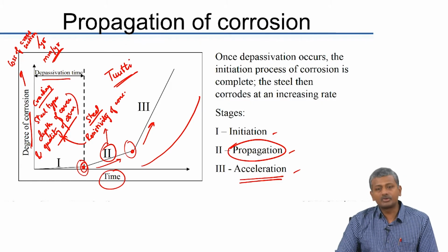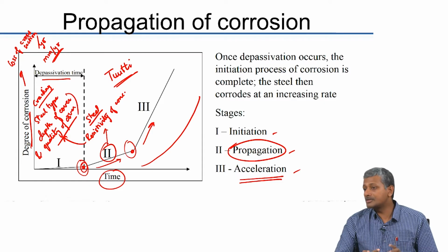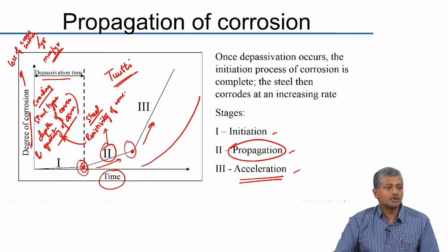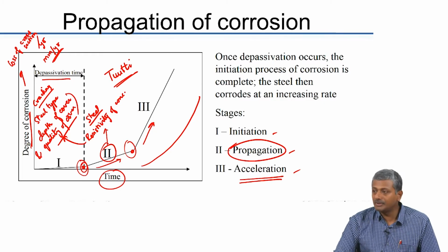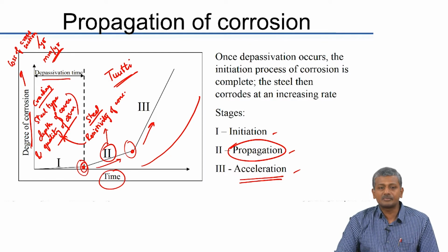Now of course that may include several different things: reducing water cement ratio, using supplementary cementing materials in case you are designing against chloride induced corrosion, right. Alternatively, you could also use corrosion inhibitors, okay, which can prolong this length of the passivation time. Of course, corrosion inhibitors can act in many ways. One of the ways that they can act is by making the concrete more watertight.